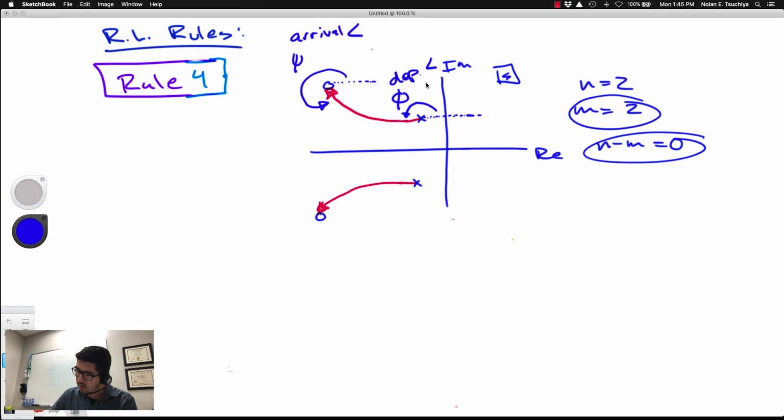Okay, so what you're finding so far, hopefully, is that the series of rules, 0 through 5, are sort of gradually giving more specificity to the root locus picture. They're fine-tuning it and making it more accurate as you apply the rules. Okay, so 0, 1, and 2, those are all broad rules. You can generally sketch out the root locus. Rule 3 and Rule 4, those are very specific, and they tell you precisely how the root locus is going to be shaped.